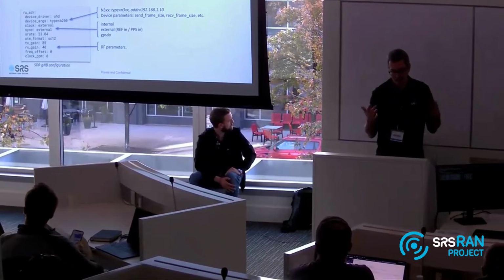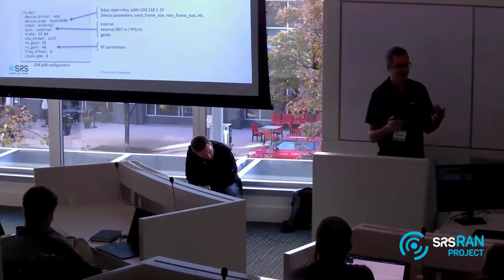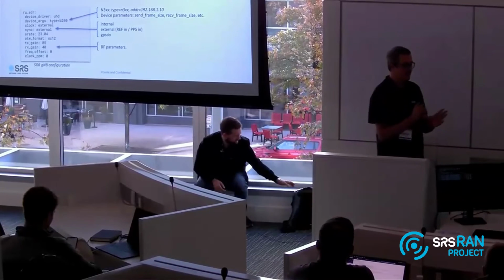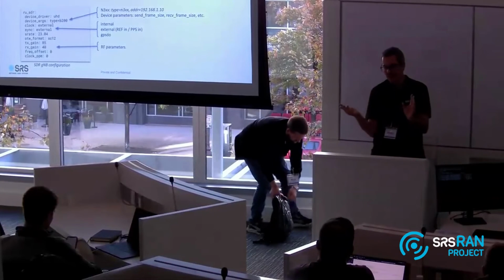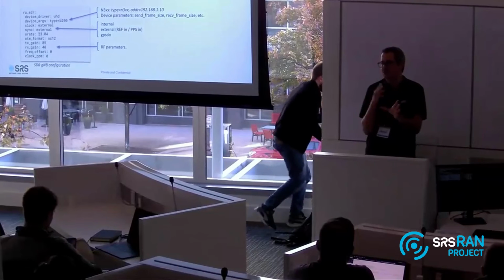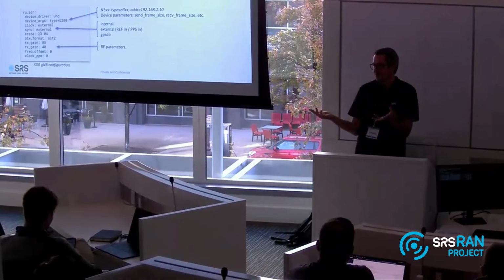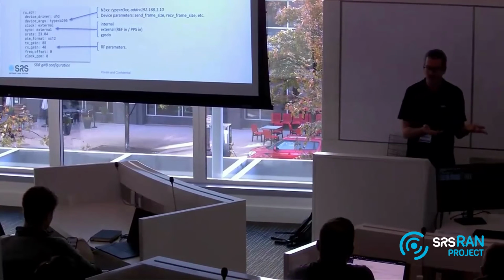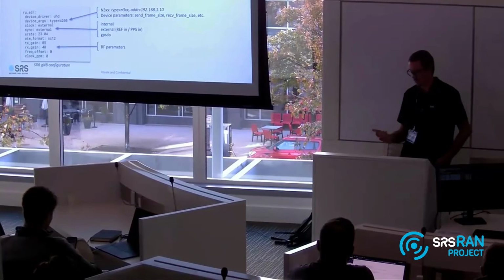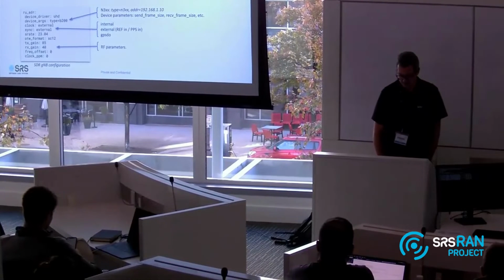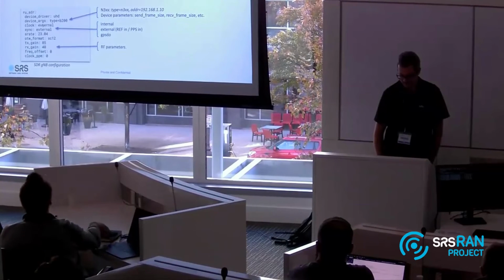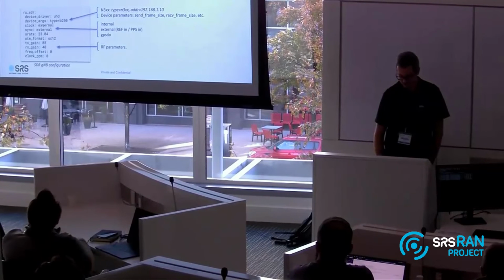And also from radio to radio, the clocks change a lot. The clocks have, in the USRP for instance, an uncertainty of 3 kilohertz. It can go in one direction, so that doesn't mean that it's always an error of 3. It can be from 0 to 3. So you can be lucky and your USRP has a good clock, or you can be unlucky and it doesn't. In any case, we always recommend to use an external clock or a GPSDO.